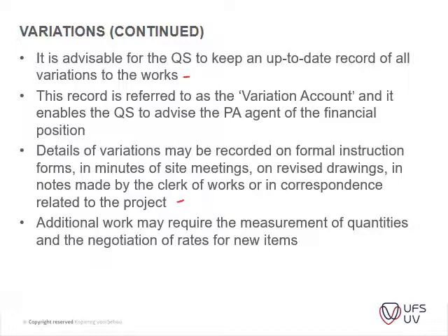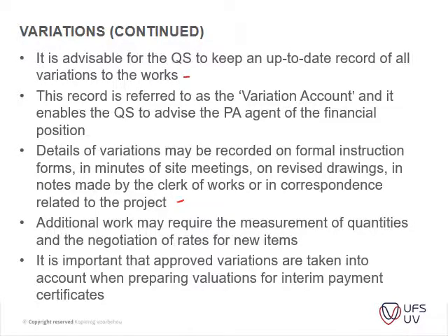It is important that the approved variation orders are taken into account when preparing valuations for interim payment certificates. This is very important. Sometimes I've seen QSs that do not incorporate these variations from the start, but leave it to the end, and that's usually where disputes come from.